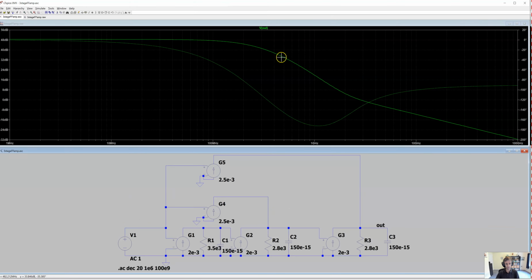So now, again, if you take close note, you would notice that the magnitude response is rolling off here at 60 dB per decade because it's determined by the third order path through GM1, GM2, and GM3 in the schematic. You'll also note the phase response goes almost all the way to minus 180 degrees. It's actually asymptotically going towards minus 270 degrees, but now there are 2 zeros introduced, so that again it bends upwards towards minus 90 degrees asymptotically, and the magnitude response also bends upwards.